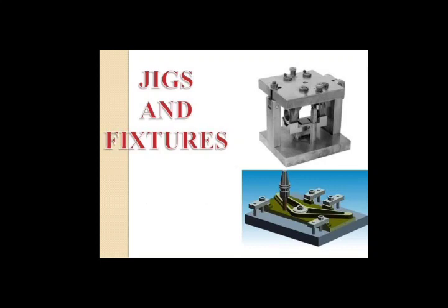The third theory to be considered is redundant location. Redundant location exists when two locators are used to restrict the same degrees of freedom from two different locations. This situation must be avoided as it may cause inaccuracy and will also cost more. For example, consider a location system for a workpiece in which both the hub and flange sides are used for location.